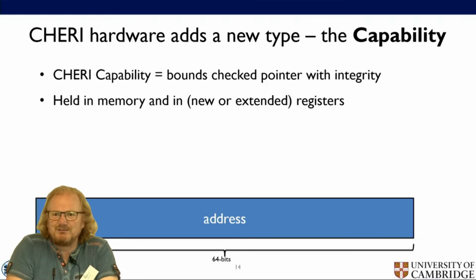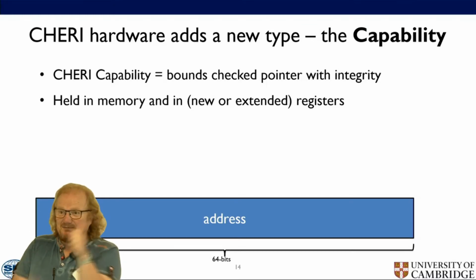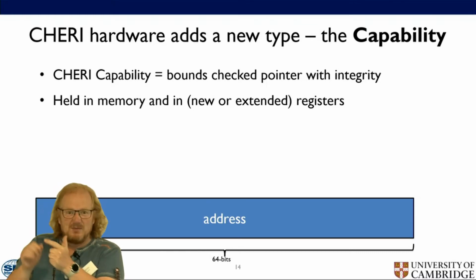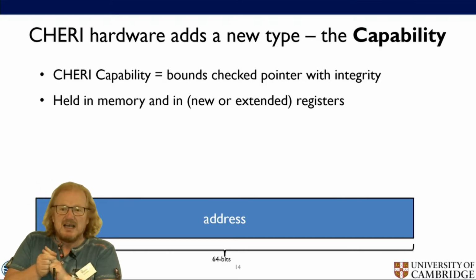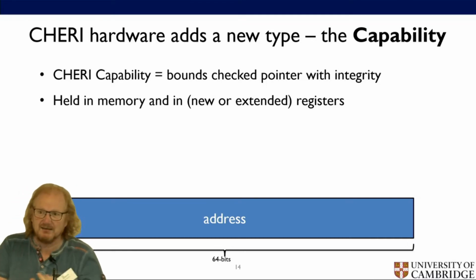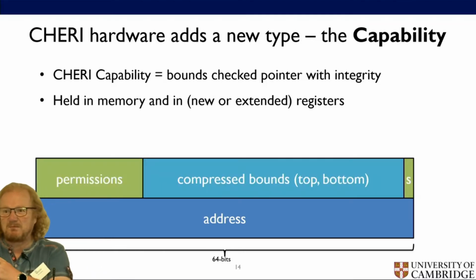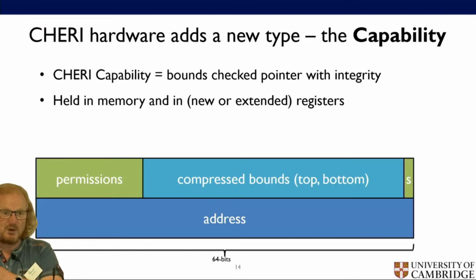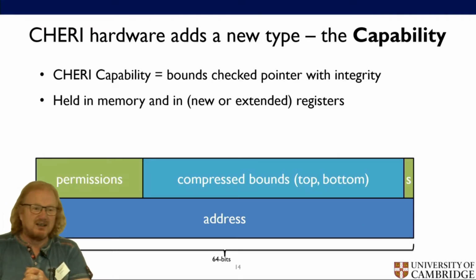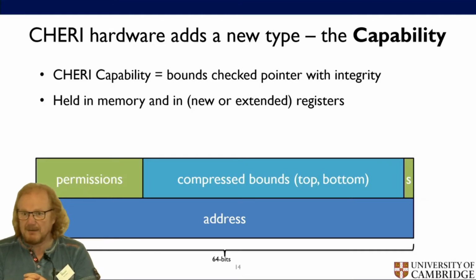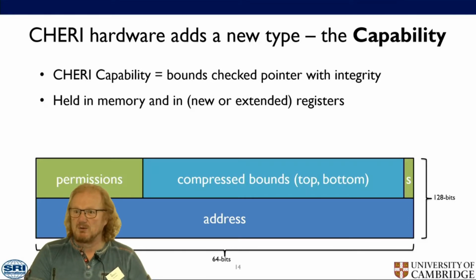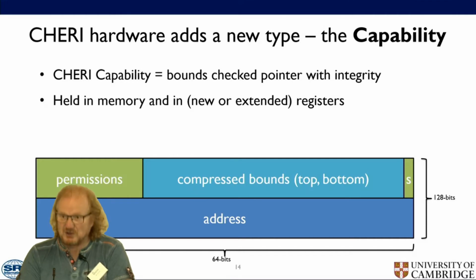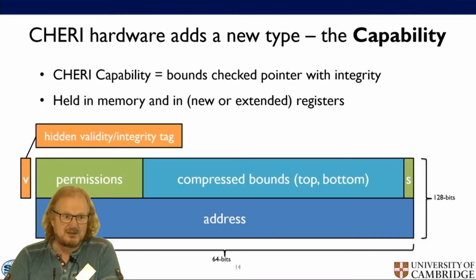We're hardware-ish people in this room. Today a CPU basically has the integer data type in different widths, and some have floating point data types. And that's it. There's nothing for the pointer data type. So if we were to create something which is a pointer, called a capability here, and set an architectural set of rules around it of what you can and can't do with it, who can use it, where it comes from, and where it goes in its lifetime, then the computer hardware natively can restrict what a pointer can do, and stop those problems of it just being an integer where you add some big number and go and scribble somewhere else, yeah?